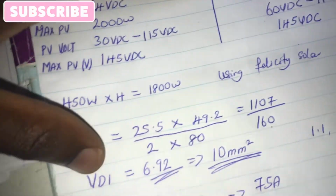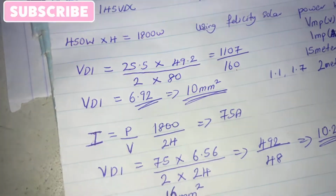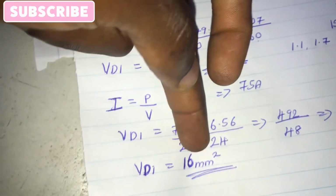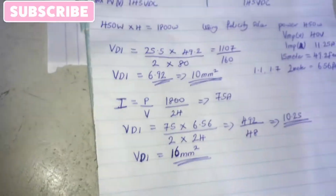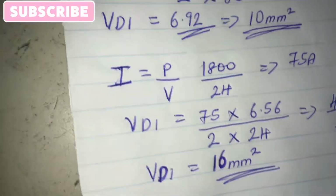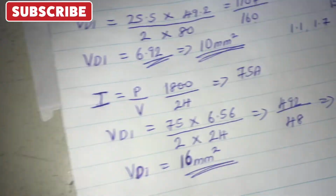Yeah, so these ones that we just did are for the DC. This one is the one that will carry the panel from the rooftop down to your charge controller. This 16 mm will carry it from your charge controller to your battery. Then the next one now is we are calculating for AC. That's the one where you connect your ACs. That's your input and output connections, the wire gauge you are going to use.